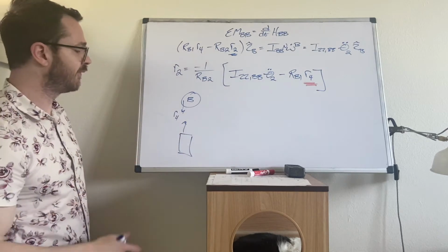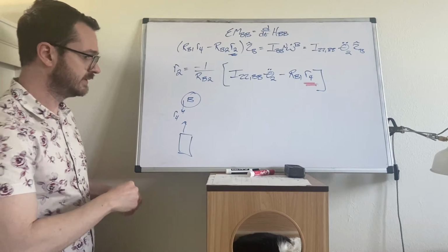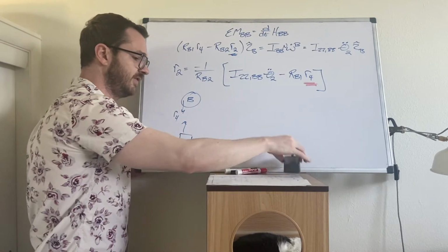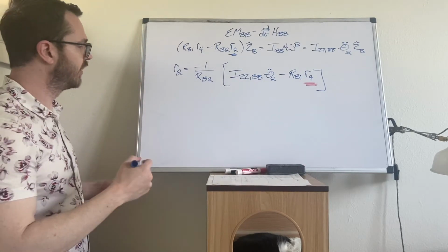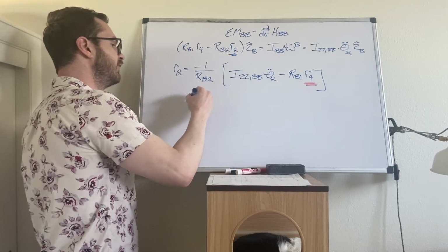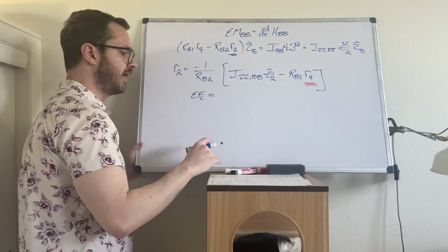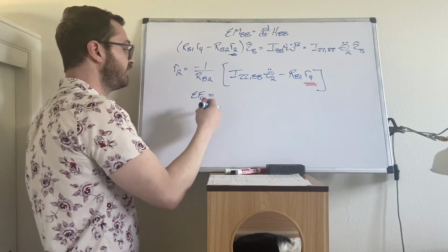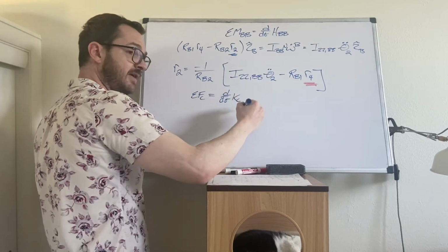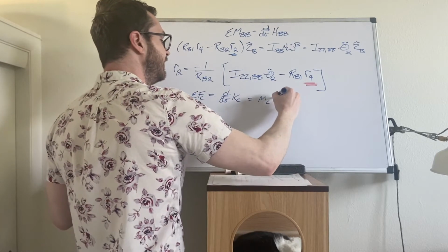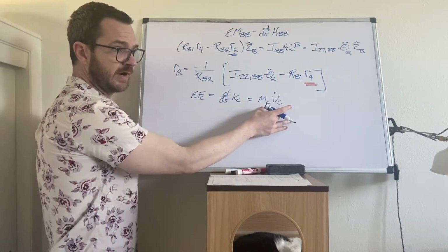So where do we get R4? Well, maybe we should go look at the equations for body C. And I can actually do that. We have enough space. These are small equations. We're going to do sum of forces on C. Remember, there were no moments and body C did not rotate. So the sum of forces on C, we're going to set this equal to ddt of kc. We know what that is. That's mc vc dot. So we've got both of these quantities defined in our notes already.